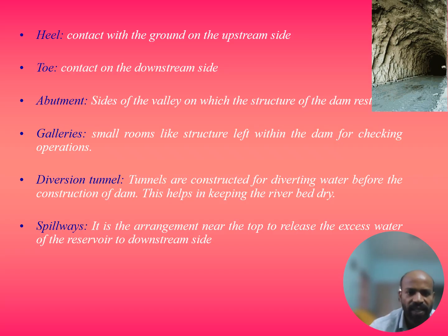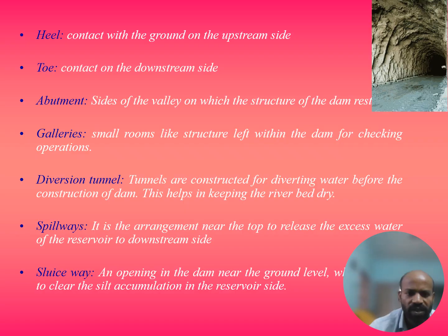Gallery. A gallery is a small room constructed within the dam for doing checking operations. Next, diversion tunnel. Before constructing a dam, the existing water is diverted by constructing a diversion tunnel. Spillway. It is there on the top of the reservoir to release excess water of the reservoir to the downstream side. Next, sluice way. It is an opening in the dam near the ground level to remove the silt accumulation in the reservoir side over a long duration of time.